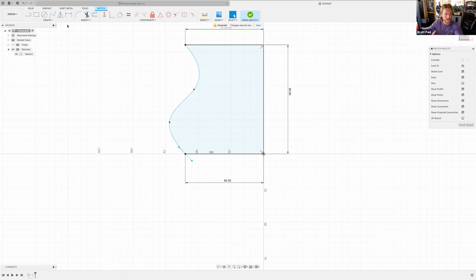We're going to go through the rest here fairly quickly. Again, I mentioned that each point has four things that we have to consider. We have to consider the handle, which is angle and magnitude, and then the point itself, which is a horizontal and vertical dimension with respect to either the origin or something that is fully constrained. Does that make sense? Can you repeat that?